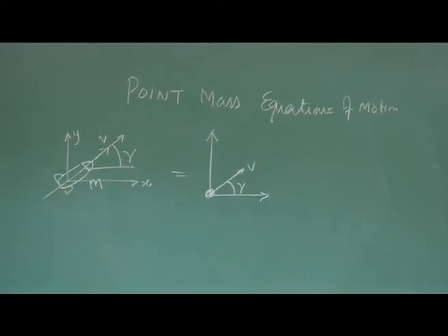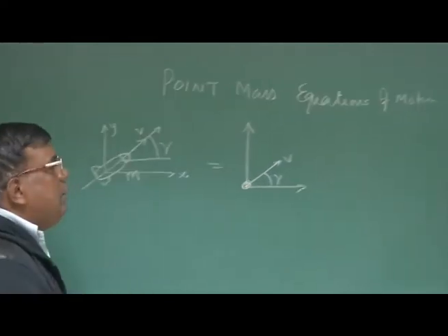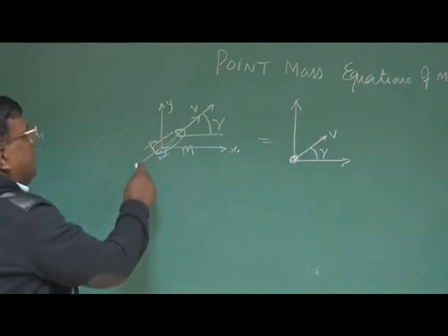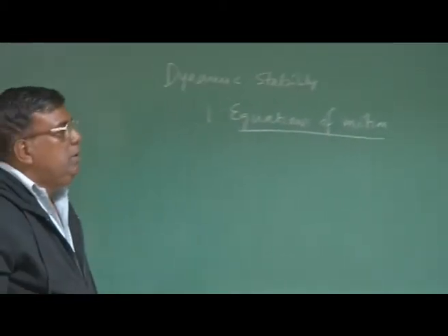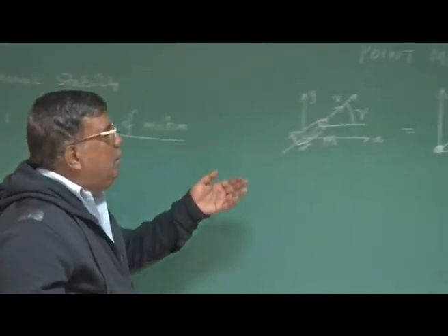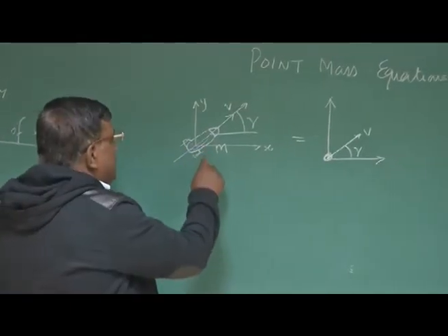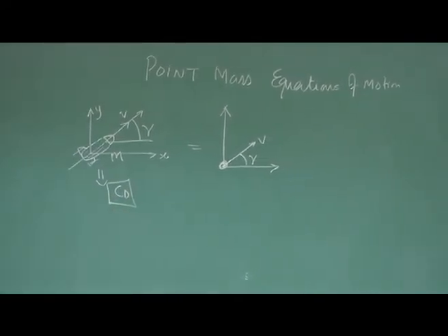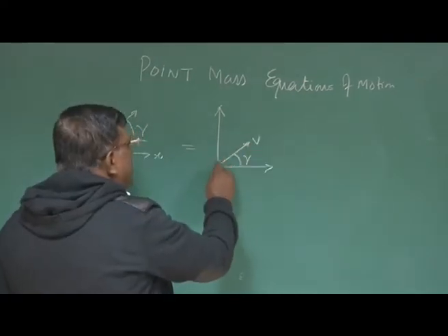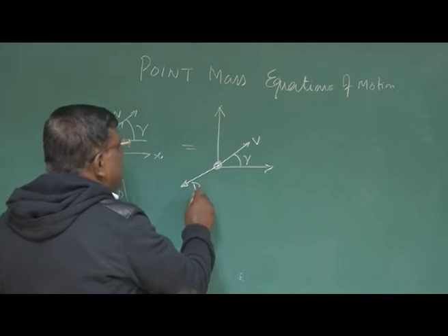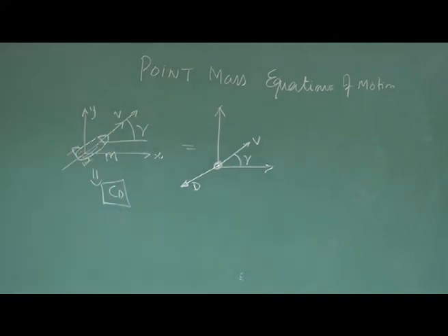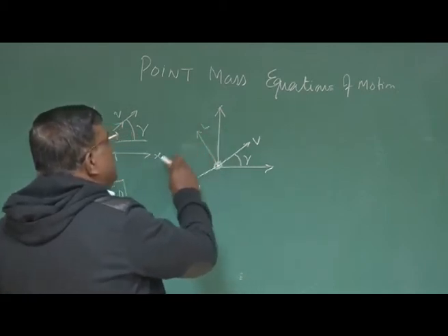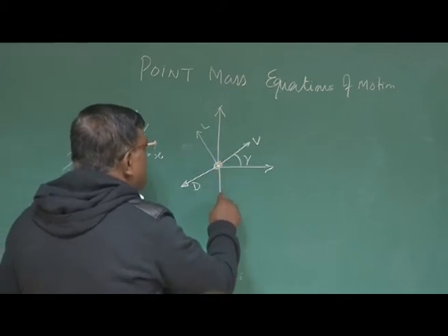And now if I write it like this, I know what forces are acting on this projectile. You know that there will be drag on the fin, drag on the body, drag everywhere; skin friction drag and pressure drag will come. So we are experts now. We know the total drag, I know how to compute it, and from there I can find the drag coefficient CD. That is known. So the drag will be in the direction opposite to the velocity. And where will the lift be? Lift will be perpendicular to the velocity vector. And there will be weight here, mg.